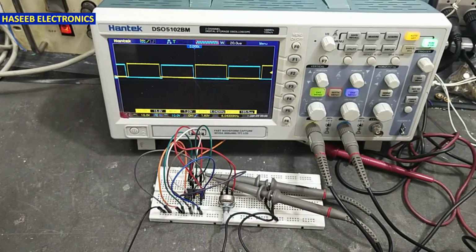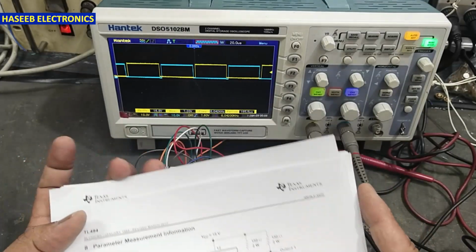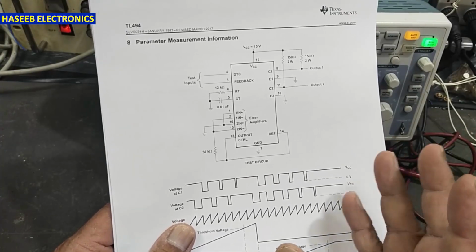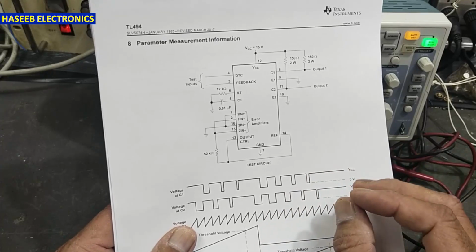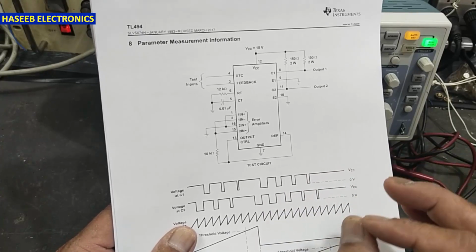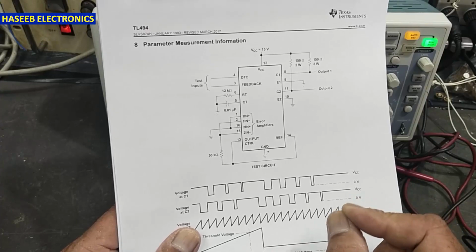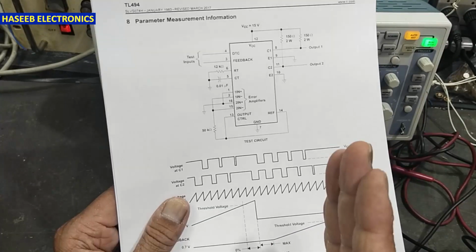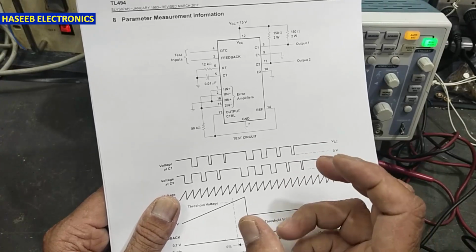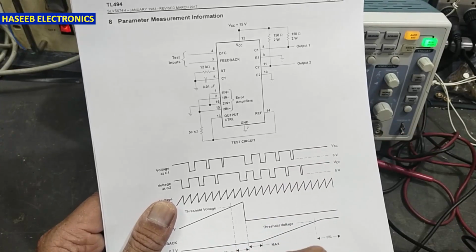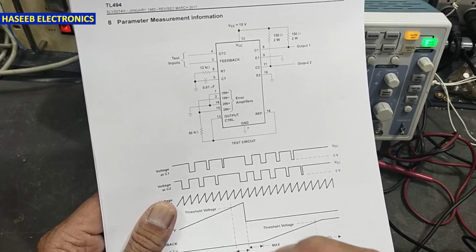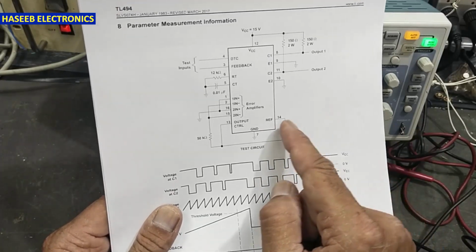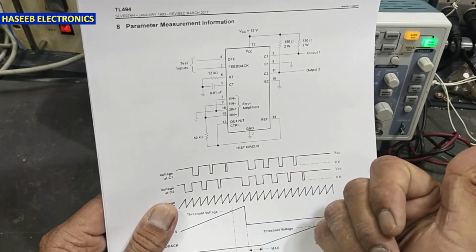Why did our friend damage 20 MOSFETs? Is the biasing for the MOSFET proper? Are you creating the dead time control perfectly? Did you calculate the gate charging and discharging resistor properly? Is the inductance for the transformer perfect? And switching frequency is the biggest item in the switch design. Are you configuring the circuit with the same frequency which you want?